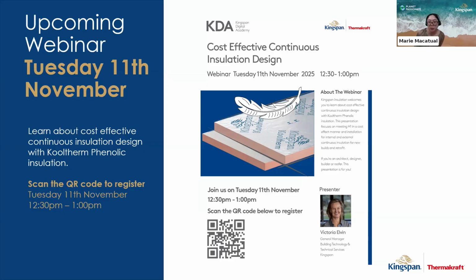Good. And what is suitable foam to fill gaps in PIR? As with our CoolTherm product, we would always say a non-solvent polyurethane expanding foam. We have a variety that people have worked with in the past, but commonly it is part of a proprietary system that will still be tested as part of their system to ensure that they have compatibility. There are some very detailed requirements about chemical interaction that are listed on our data sheets for PIR as to what chemicals cannot be used, but as a general rule, a non-solvent polyurethane expanding foam would be ideal to fill the gaps that you might see between insulation materials.